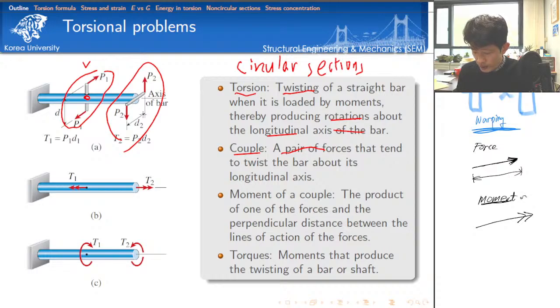For example, like this. In the case of force, we use one arrow, but to represent the moment or the torsional moment, we use double-headed arrows. The direction that the double-headed arrow tip represents is the direction of my thumb. So we are using the right-hand rule. To you, it doesn't look like my right hand. Okay, this is my right hand. Direction of thumb, and this is the direction of the torsional moment.